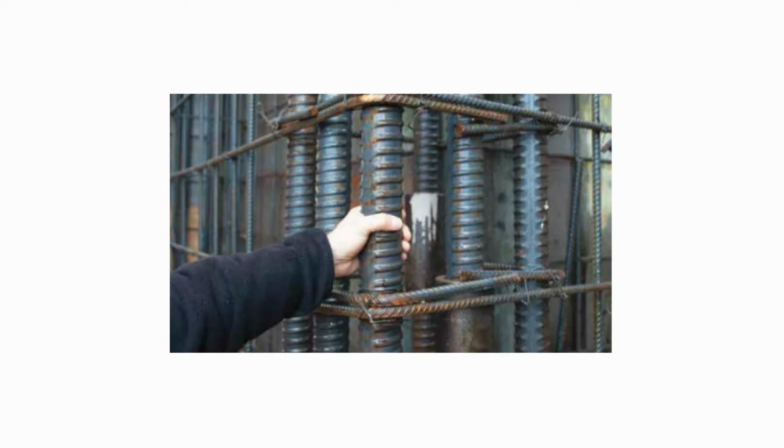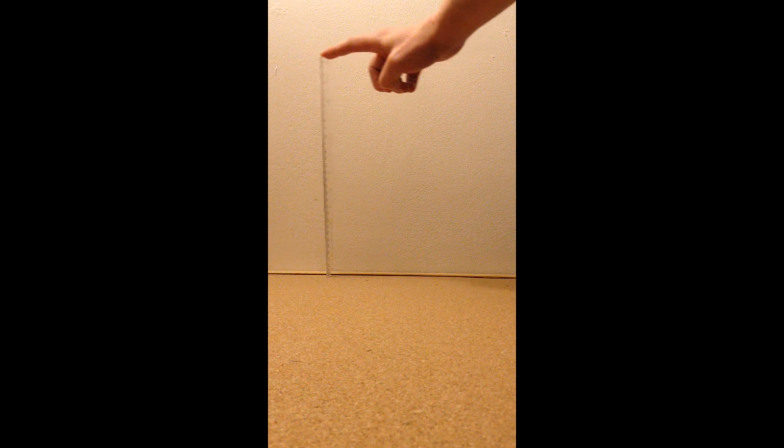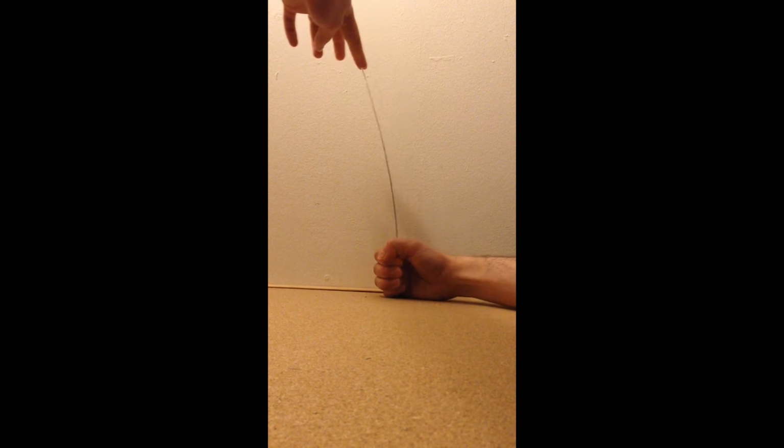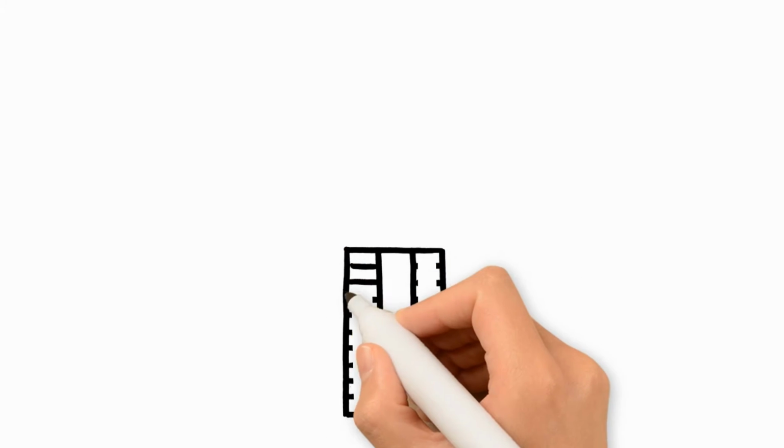Even with this system, the slenderness of the tower still makes it vulnerable to swaying in the wind. To increase the stiffness of the structure, a large amount of steel reinforcement is present. The reinforcement bars in the columns are 6 centimeters. In addition to vertical loads, towers also have to resist horizontal forces, like wind forces, for example. Most towers have a central core that resists these forces, just like this ruler. In order to remain as slender as possible, 432 Park Avenue uses 2 tubes.